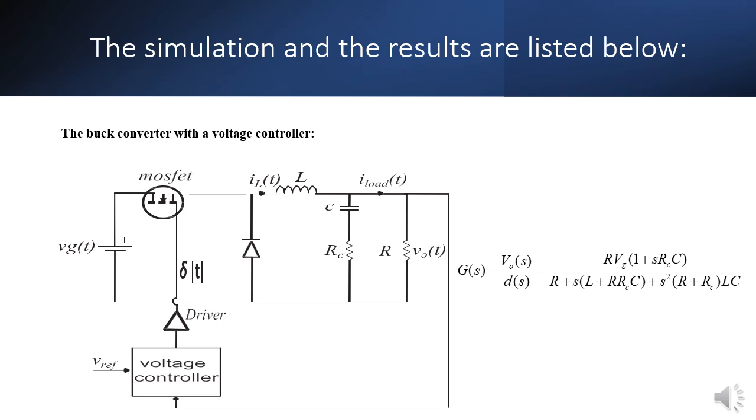The converter includes an output low-pass filter made up of an inductor with inductance L and a capacitor with capacitance C to filter the output voltage. The higher input voltage relative to the output voltage causes the inductor current IL to increase when the transistor is turned on during buck converter operation. Since the inductor current cannot stop instantly when the transistor is turned off, the diode begins to conduct. The inductor current decreases because the diode is conducting, when the voltage across it is zero.